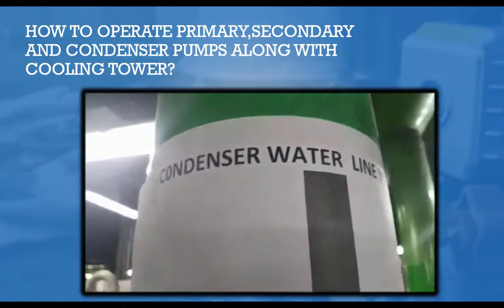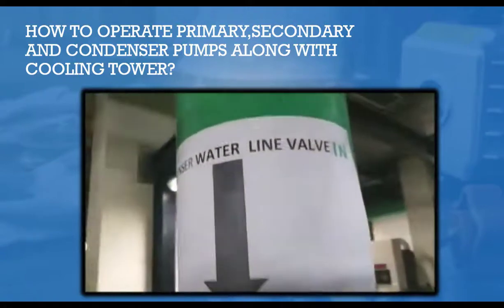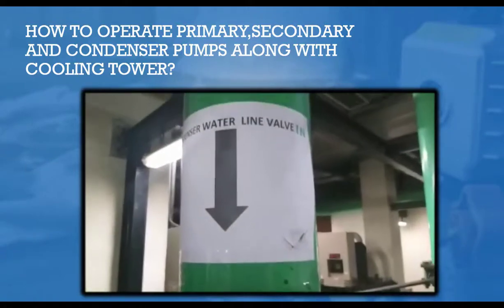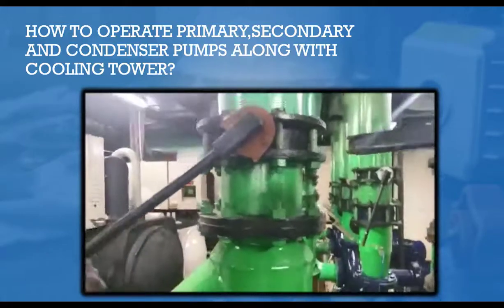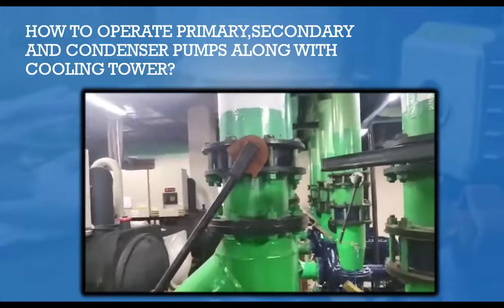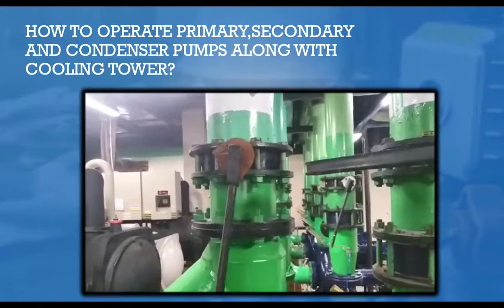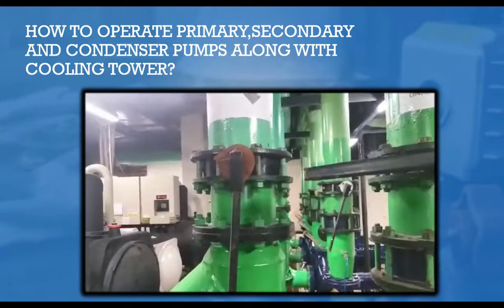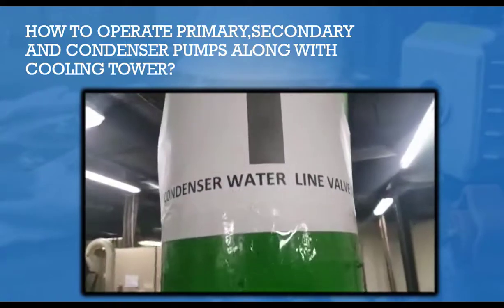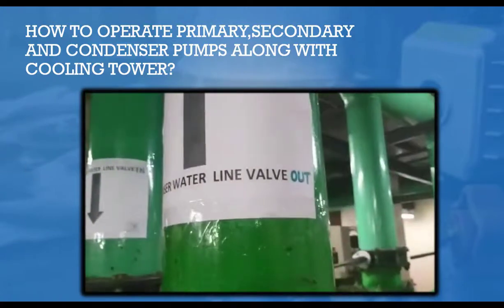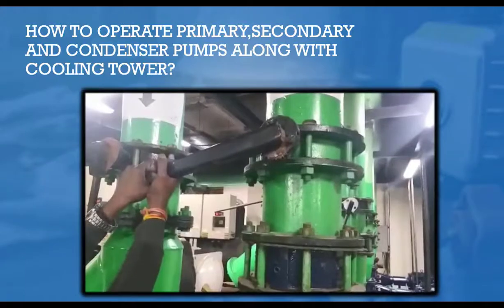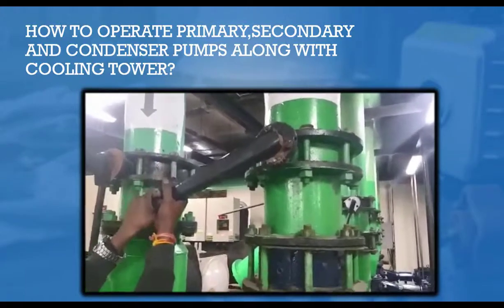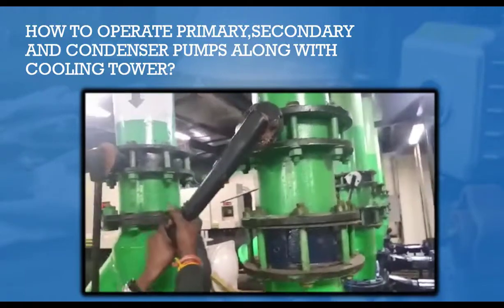Same way, the condenser pump inlet valve and outlet valve should be open. Ensure water flows freely into the cooling tower.